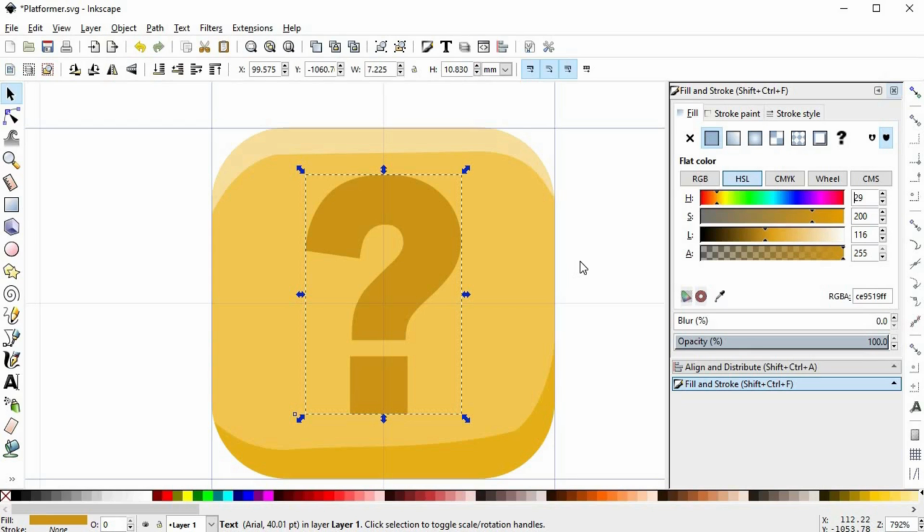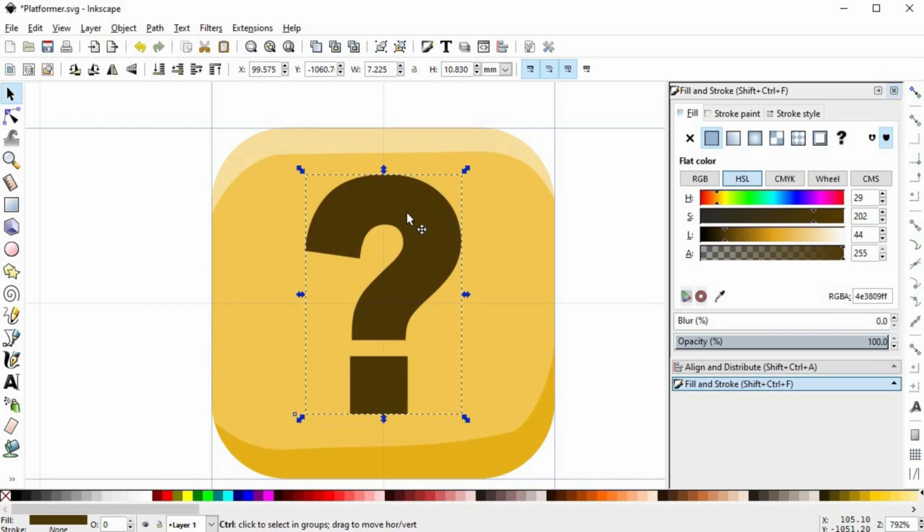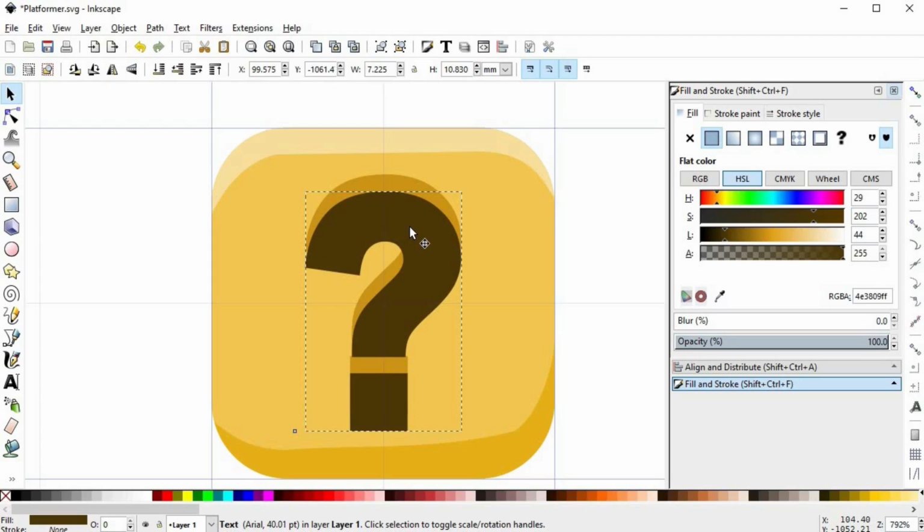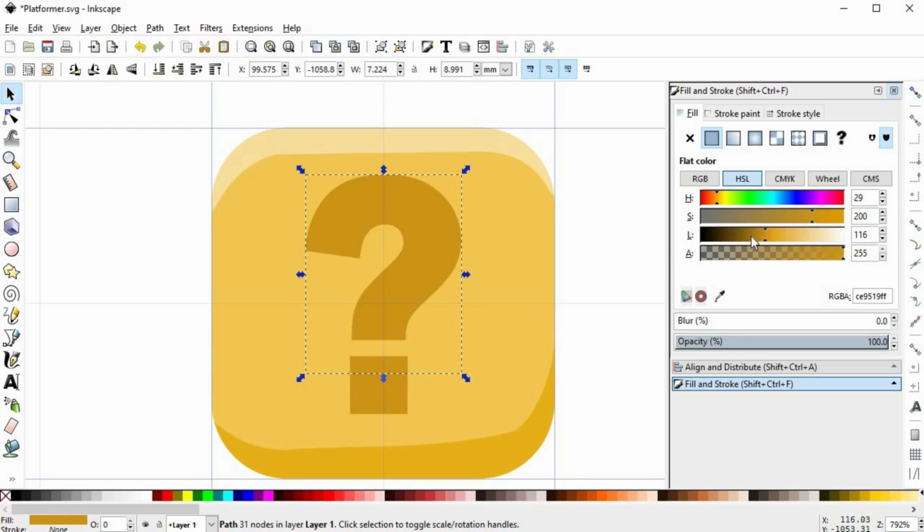Let's start with the shadow. For this we are gonna use the difference technique that I showed you in the technique lesson 1. Rewatch that lesson if you are feeling a bit lost. So duplicate the symbol twice and make the top symbol of a clearly visible random color. Move the top symbol a bit down. Remember that the area that's showing through is gonna be the shadow. When you're happy, select the top symbol and the symbol right below and perform a difference. Now it's just a matter of giving the shadow a shadow color.